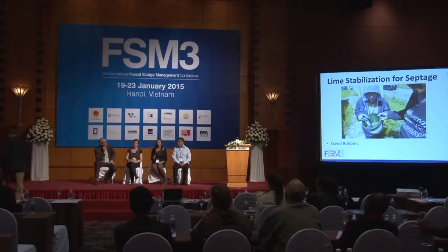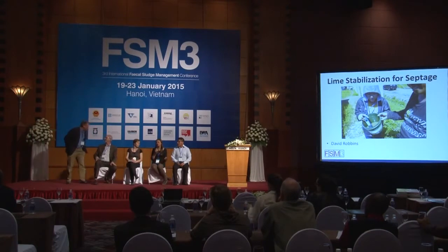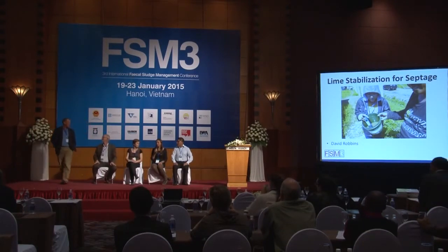Ash would work in a similar way by raising the pH, but it doesn't get anywhere near the 12, and 12 is the killing zone that we're trying to achieve with lime. Also, regarding the source of ash, if you're in an area where there isn't a lot of wood burning or you don't want there to be a lot of wood burning, it could be a limiting supply. So it would be a different application protocol.